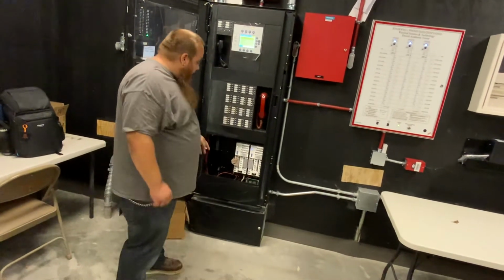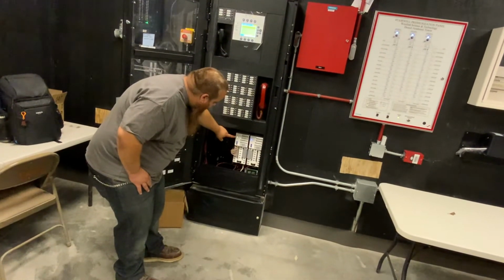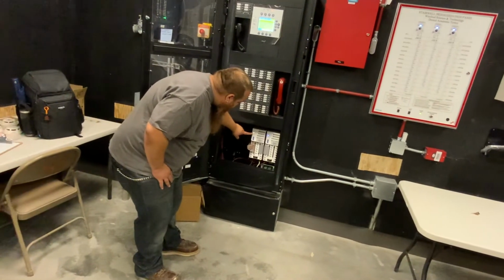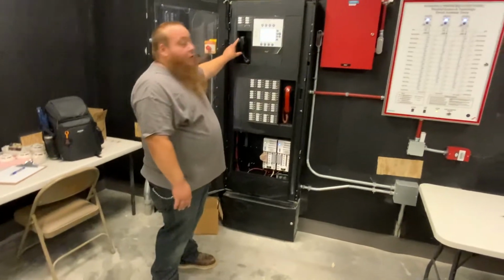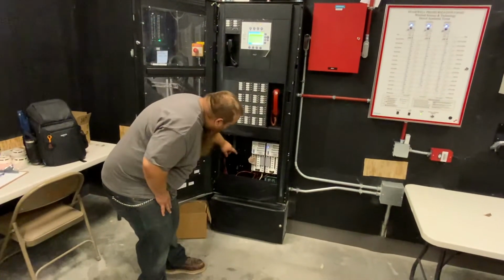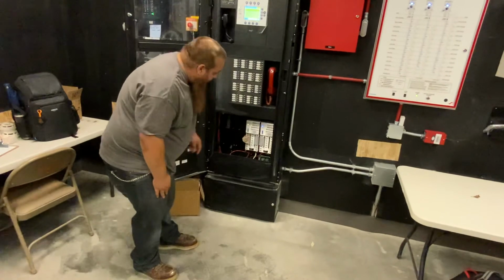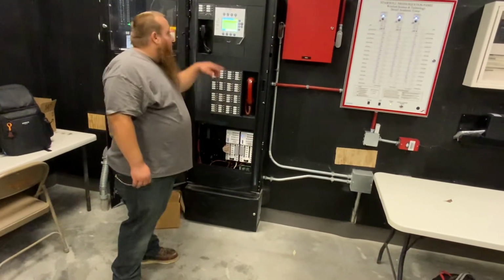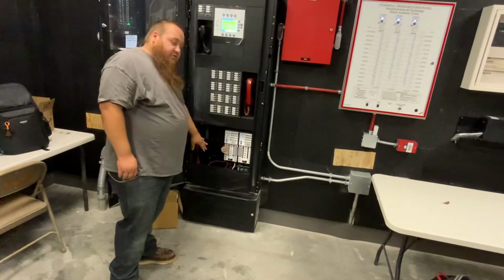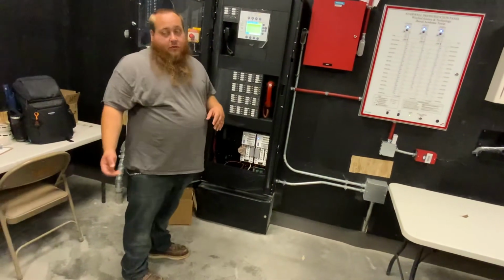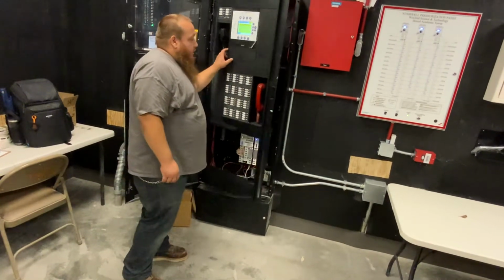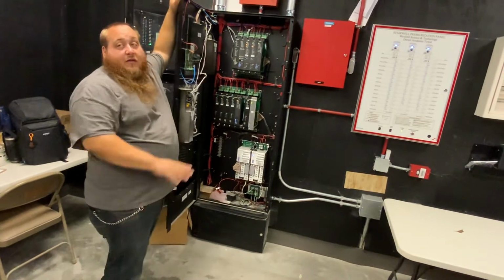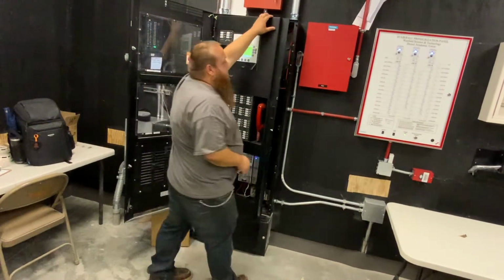Even if you have a bad power supply, you'll notice that you have a power fail, module fail, CAN fail. HNet fail would be your communication. Your CAN will be all your voice related components. You have a ground fault lit as well. So say if there's a ground fault on this panel, it'll light up here and also here, but that'll help you identify that it's just local to this panel, not out in the field. If you have a ground fault on a card, that means that the ground fault is located somewhere out in the field. So that's how you'll be able to differ where it is.